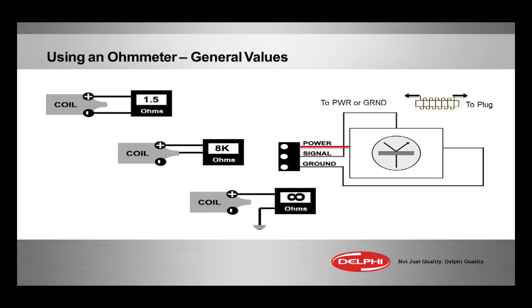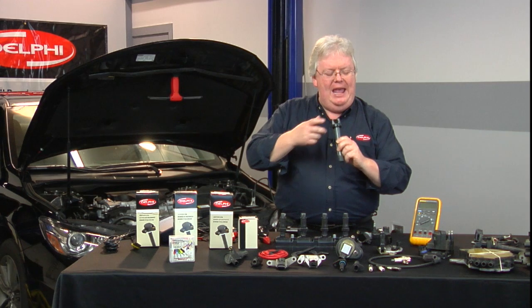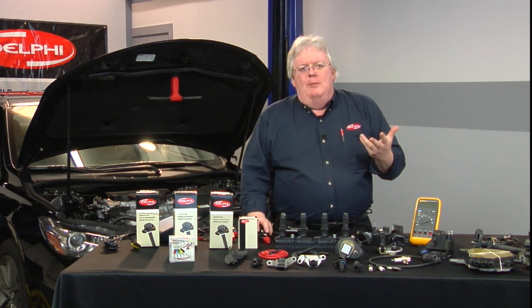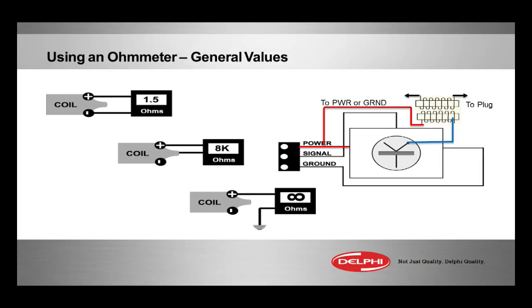You see several thousand ohms, things you can't do with the Coil-On-Plug 3 and 4-wire circuits, because of what you see in the schematic on the right, where I'm starting to now have the power lead going to the bottom side of that primary winding and goes over and captures a spot where the ignition feed is to the coil terminal itself, the connector, and then the ground provided by that NPN transistor, the coil driver, built into this guy right here.